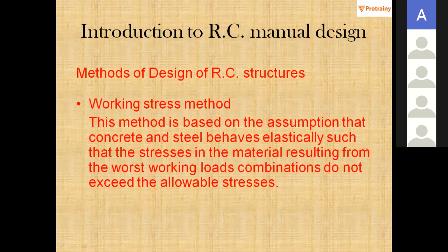So nowadays this method is used for dams, bridges, anything other than a multi-story or high-rise building. Because if you want to design a frame structure according to the working stress method, your beam will be like 10 feet deep, and this is not feasible. It can't be done. So the working stress method is nowadays not applicable to frame structures.